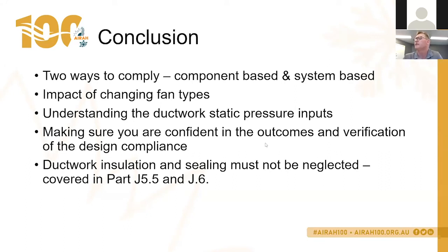What's the relevance of watts per litre per second for the fan selections? Is it now just about fan efficiency? That's a fairly difficult question to answer quickly, but there was a large amount of detailed analysis, energy modelling work and fan efficiency assessment work done before the 2019 code was written. It was believed that the 2019 code was actually going to be slightly more stringent than the 2016 allowances.